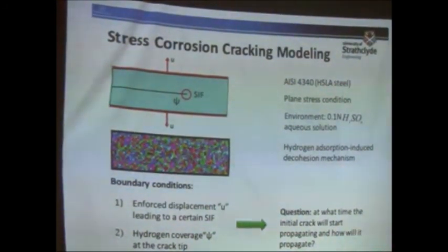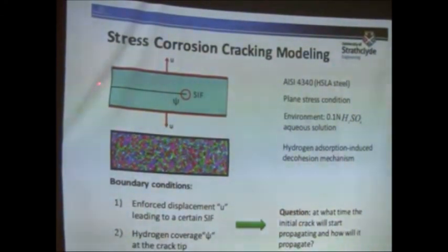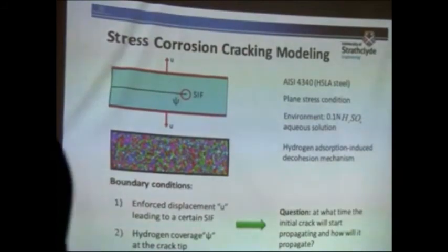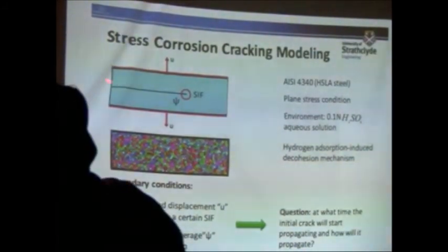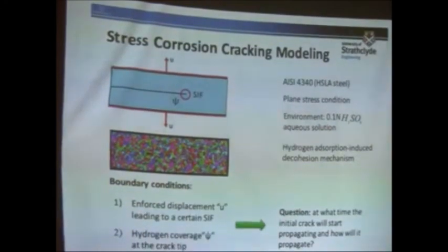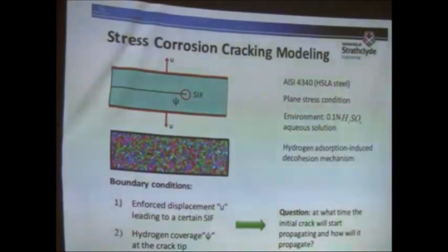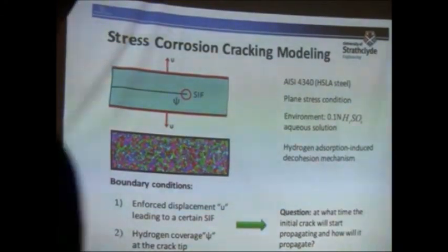It is made of a high strength steel, and we have an initial crack somewhere here. We are applying a displacement load at the top and bottom, under static conditions. And again, we just take into account the polycrystalline structure. Here we have a corrosive fluid inside of this crack, but the good thing is almost all of the surface is painted, so there is no influence of the corrosive fluid on the structure itself, but this tip is free. It's not painted, so the corrosive fluid can interact with the material at this particular crack